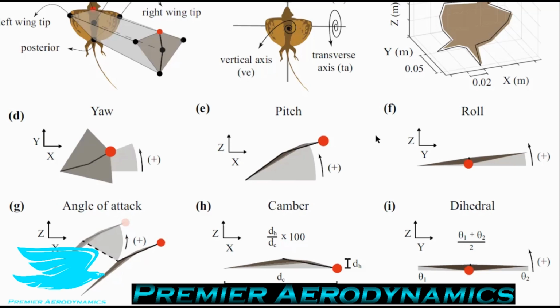So why is that? The reason is because if you think about your wing, let's say you've got your hand and you have it palm up. So now this is your platform, and you bend your hand at the knuckles. Your fingers will be one side of the wing, your palm will be the other side of the wing. So that's dihedral. Now, if you rotate your hand about the knuckles axis, the one wing will go higher, the other wing will go lower.